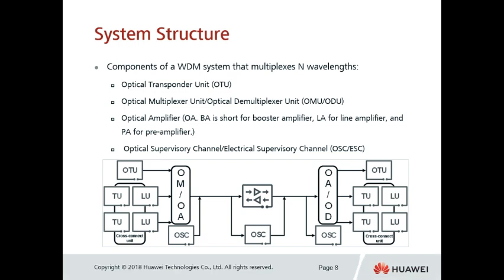The OTU maybe cannot receive it, cannot detect it. So before we use the OD demultiplexer, we need an optical amplifier in the same station to make your service signal a little higher. Then we can do the demultiplexing. So we have OA and OD in the destination stations. And OD will drop all the wavelengths and give them to different OTUs, depending on the frequency. Each frequency for its OTU will be connected by fibers.